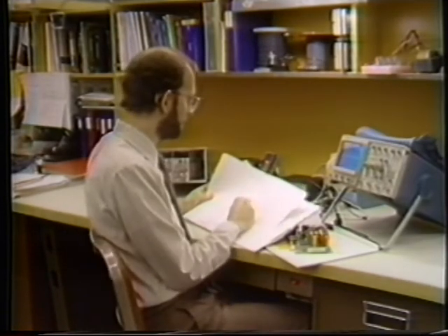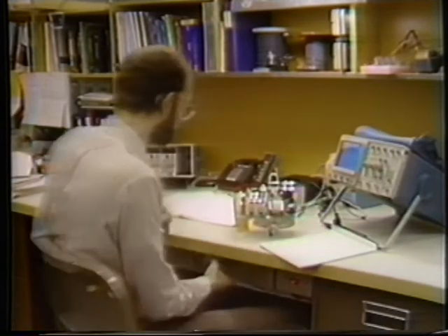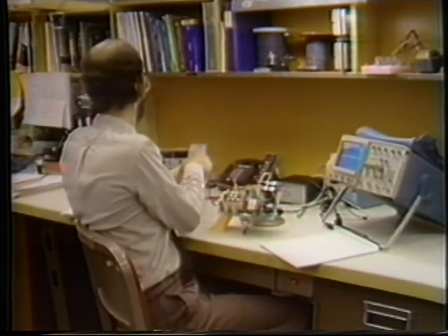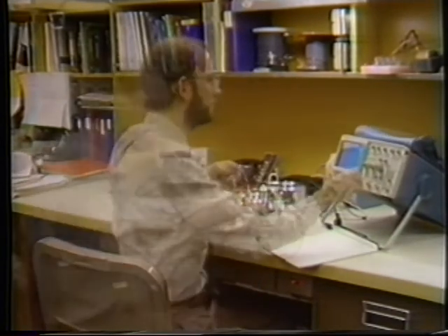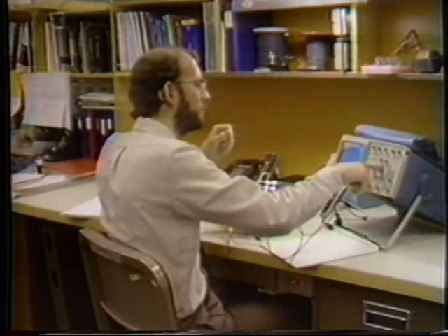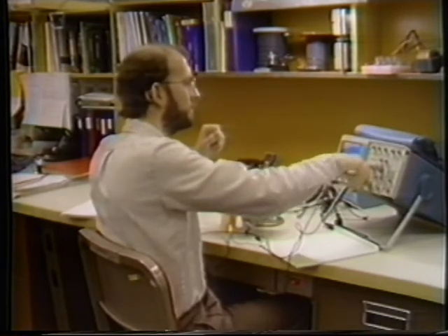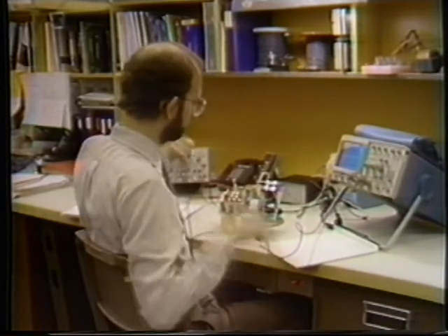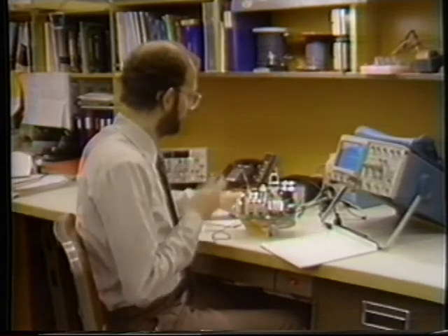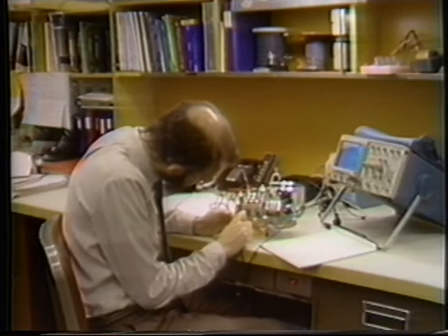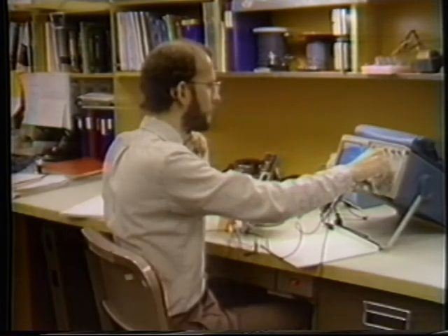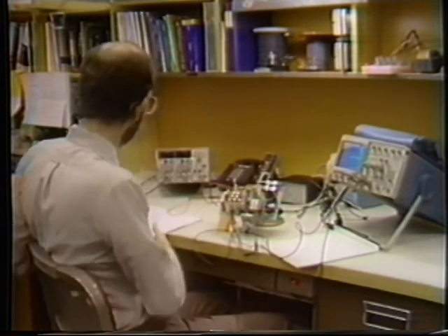First, how do you determine the voltage? Well, you need to measure voltage across the transistor, not to ground. That's right, a differential probe or similar strategy across the transistor from collector to emitter. Great, but now how do you measure the current? Okay, you could try measuring the voltage across an existing known resistor and derive the current since I equals V over R. Or you could insert your own resistor into the circuit.